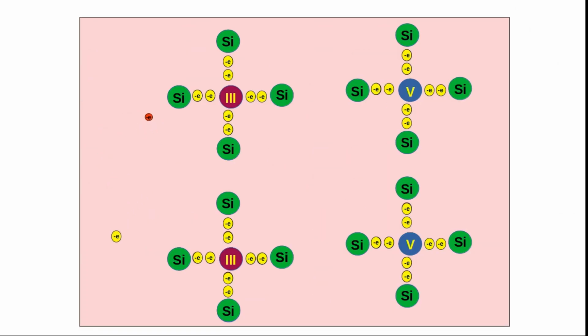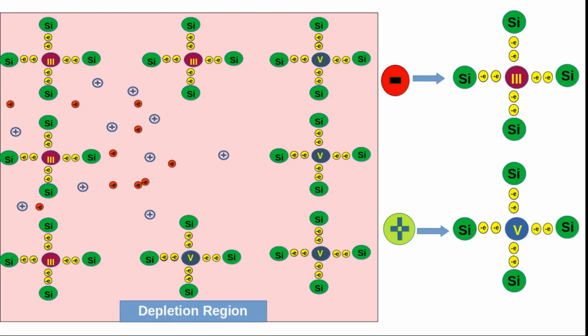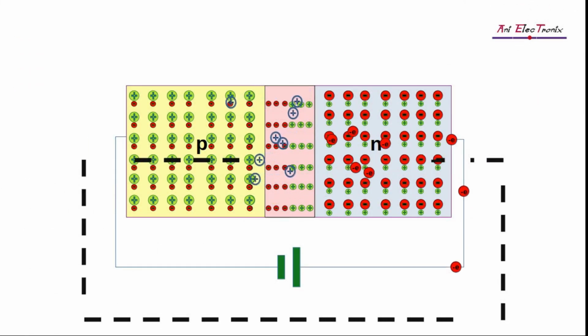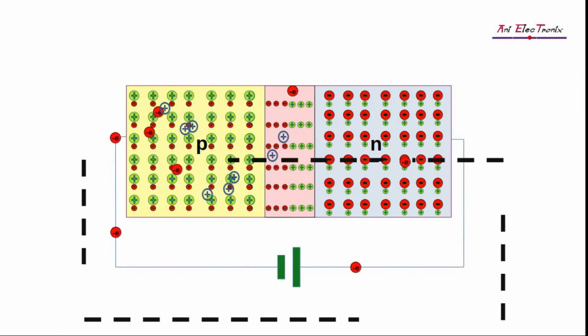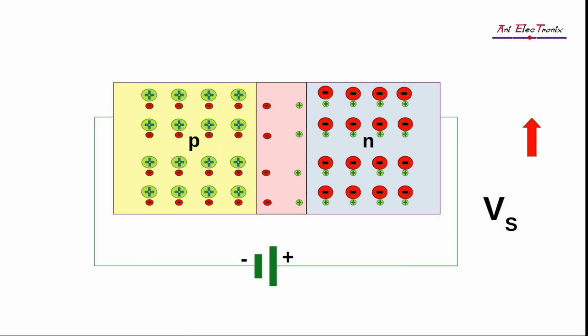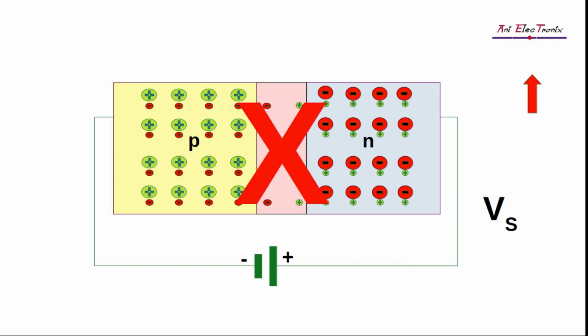Therefore, the newly formed carriers combine with existing minority carriers in order to collide with other atoms and knock out the valence electrons. In the beginning, there was one electron, but upon collision, two electrons emerged. The free electrons accelerate and displace another two valence electrons from the atoms, creating a total of 4 free electrons, and the process continues until the reverse current is enormous. This is known as avalanche effect. The avalanche effect causes the diode to conduct heavily due to the sudden appearance of minority carriers in the depletion region.